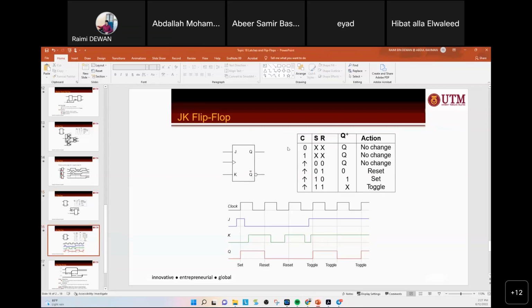Where were we? So here we have 0, 1. Again, because this is a flip-flop, it doesn't change when there are changes in the clock state, but only when there is a change in the edge. And the edge we are referring to here is the rising edge, not the falling edge. It depends on what kind of edge the flip-flop reacts to. If you have a bubble here, it means it will react to the negative edge trigger.